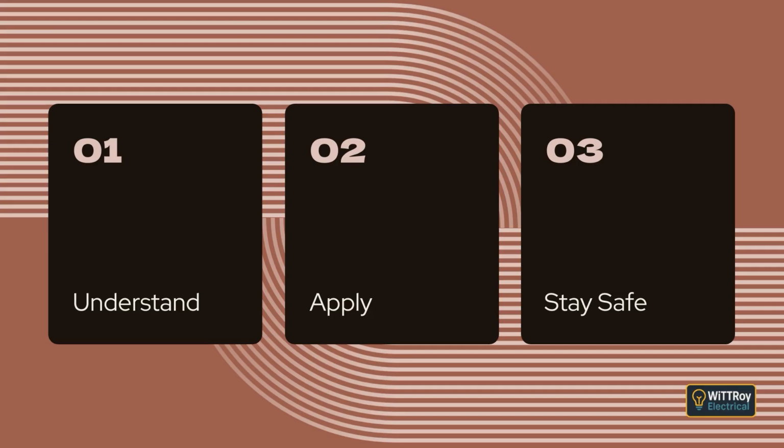Clause 3.3.2.3 Presence of water or high humidity. Wiring must be chosen and installed so that water or moisture does not cause damage. If condensation can form and become a hazard, the system must allow water to drain safely through suitable outlets. If the wiring may be exposed to wave action or similar forces, it must be protected from excess movement and mechanical stress, using the other clauses that deal with mechanical protection.